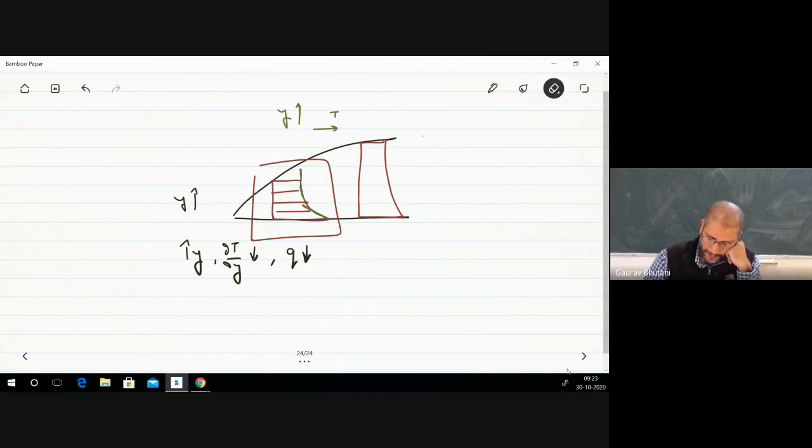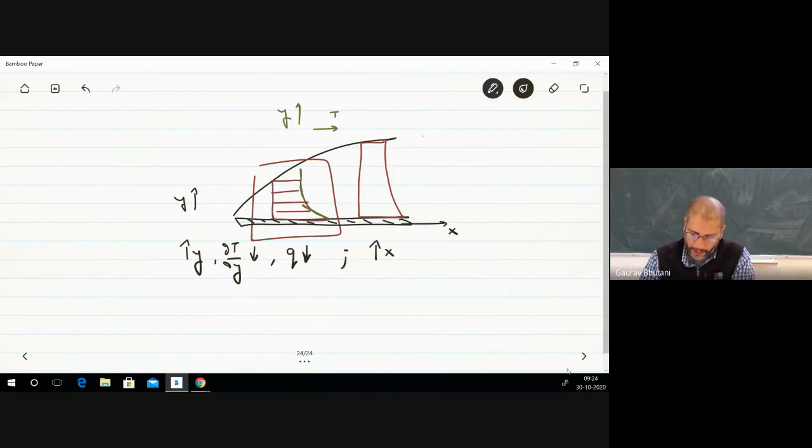But again, the other thing we talked about was as my x increases. In this case, you have this x coordinate along the plate. So as your x is increasing, the gradients of temperature on the wall, which is this one, if I compare this line with this line, I see that the gradient on the wall is also becoming gentler.